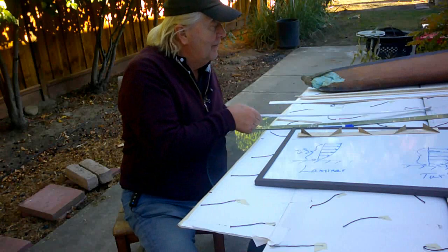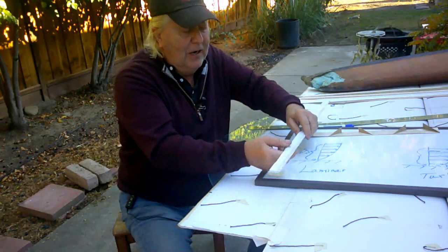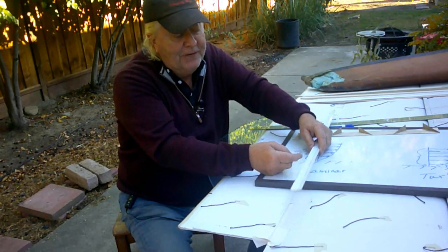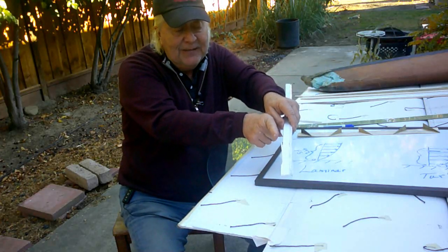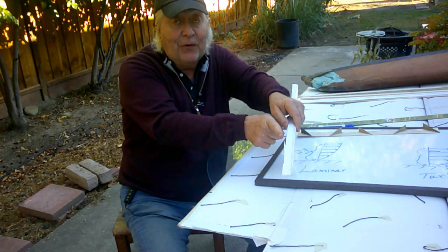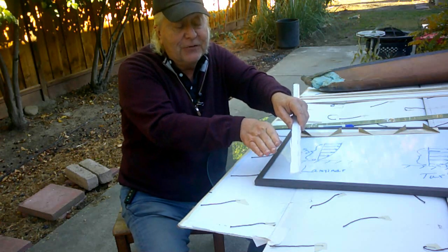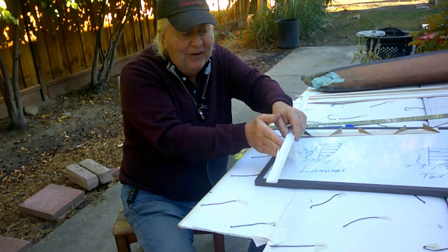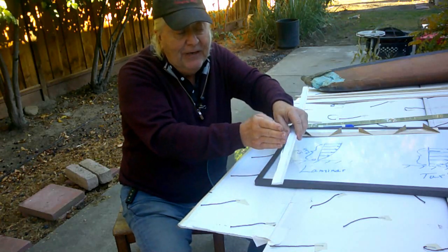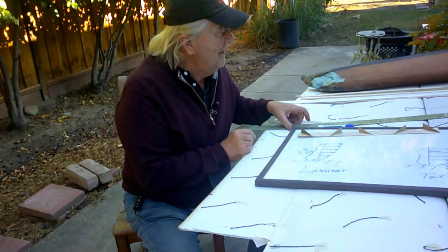Okay, this guy. You drop off the ledge here on the back side, or the flow tries to go straight, and you get a little tiny vortex that forms in here where the flow is detached. And the vortex can scoop up energy out of the flow and carry it into the boundary layer. That's all theory, and that didn't work for crap either.